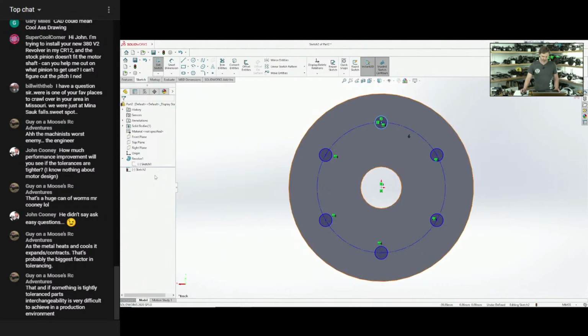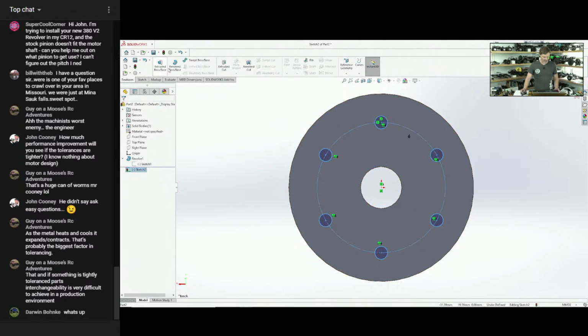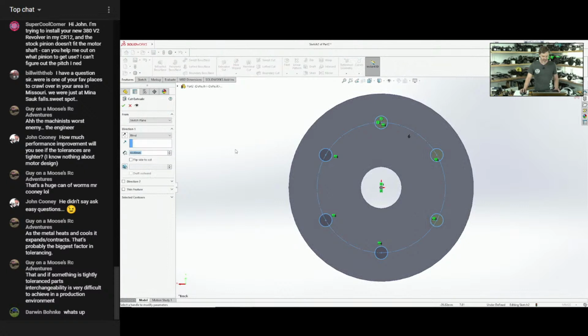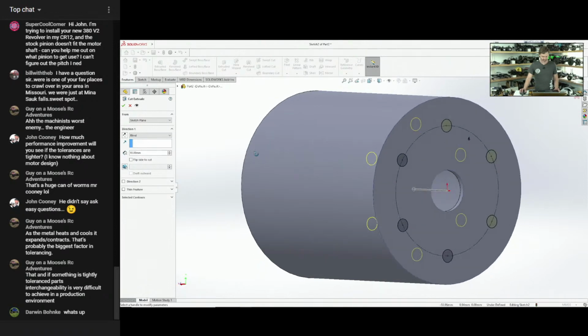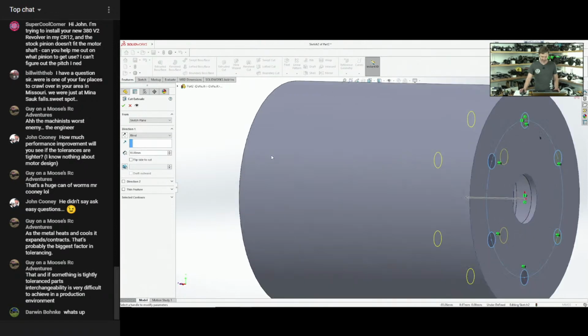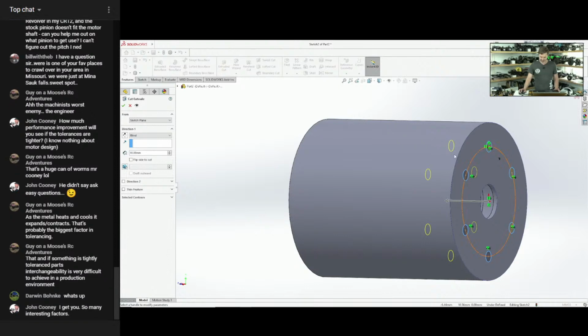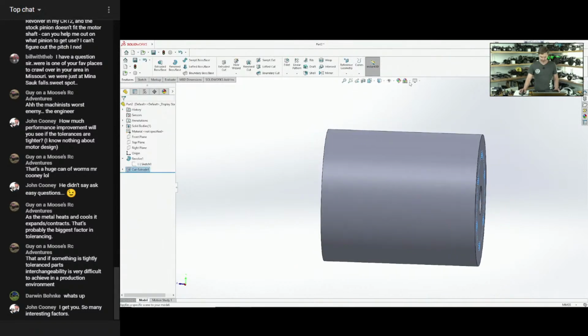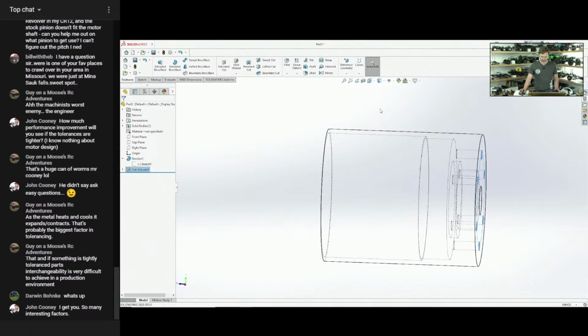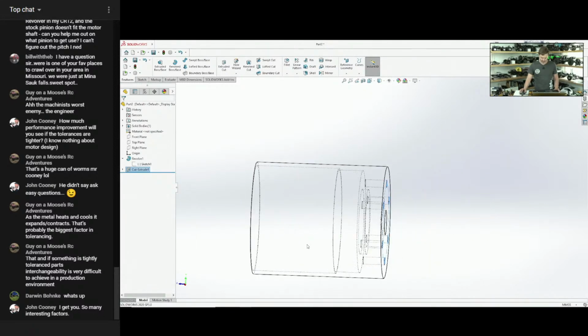So I'm just going to do 4 circles in the sketch and then go back to features, and we will do an extruded cut, and it should select all of those for us. Yes, and it automatically selected 10 millimeters because that is our standard. And I know, since I did an 8 millimeter thickness of the faceplate, that I can do a 7 millimeter extrusion. We're going to hit OK on the extruded cut, and then go back to our wireframe and make sure.